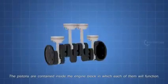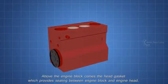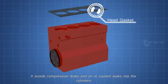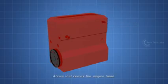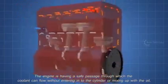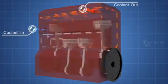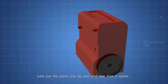The pistons are contained inside the engine block, in which each of them will function. Above the engine block comes the head gasket, which provides sealing between the engine block and engine head. It avoids compression leaks and oil or coolant leaks into the cylinders. Above that comes the engine head. The engine has a safe passage through which the coolant can flow without entering into the cylinder or mixing up with the oil. This passage is known as the water jacket. Let's put the parts in one by one and see how it works.